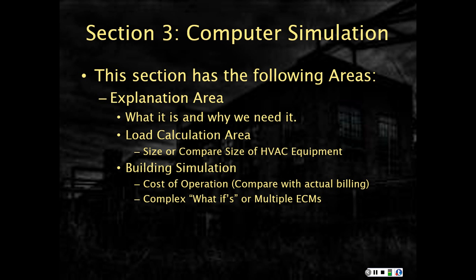When I did the bonus review on the carrier HAP program, I went into the HVAC equipment and showed you where we can change efficiencies. It's really crucial that we use the carrier HAP program to do things like efficiency changes, because this equipment isn't running all the time.